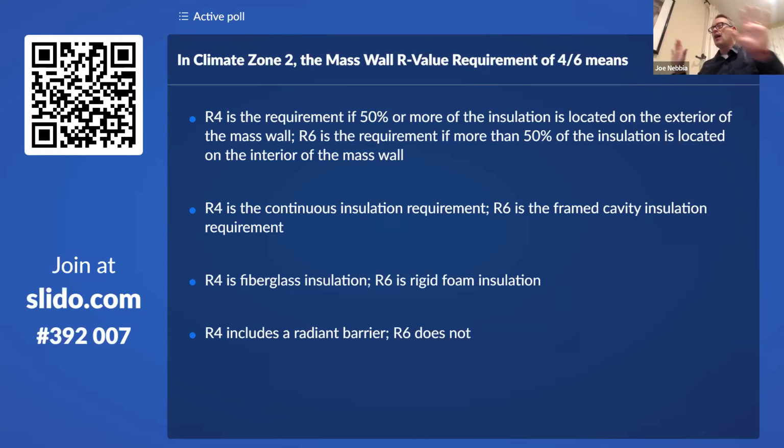If you spray enough that you've got a continuous layer below that ridge line, you may be able to do a U value calculation and get some amount of trade-off there. More than likely, you're going to have to do a UA compliance because spray foam's expensive and you're not going to put a ton of it in the ridge line. So you're going to add insulation in the walls or better windows to do a UA trade-off and comply there.